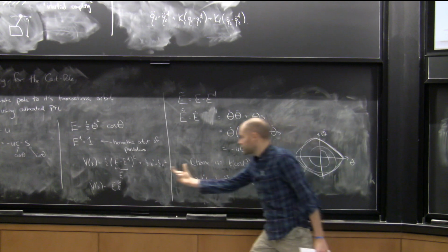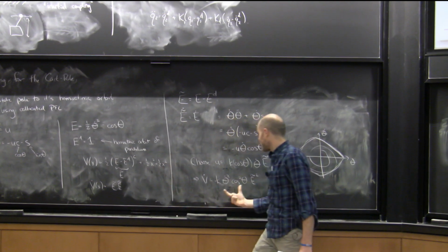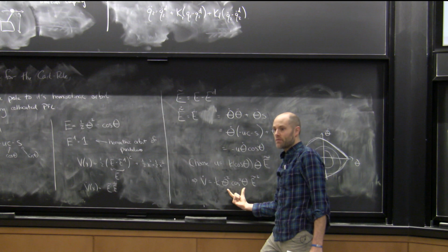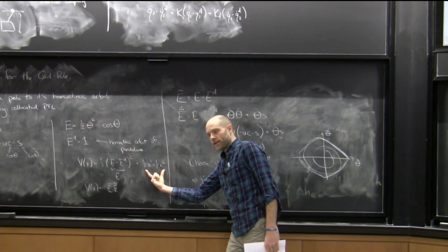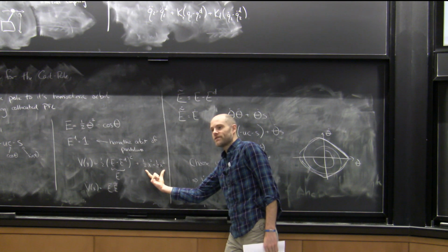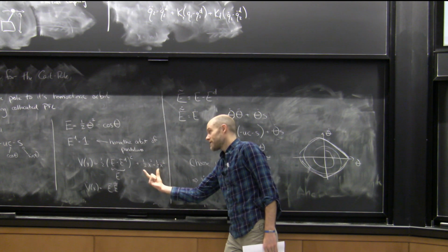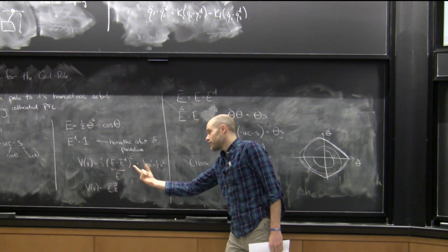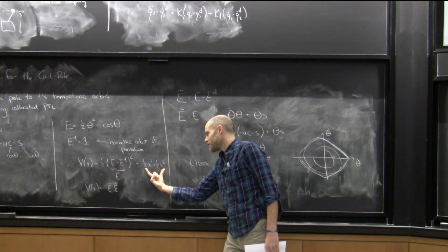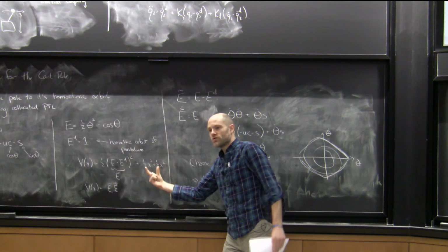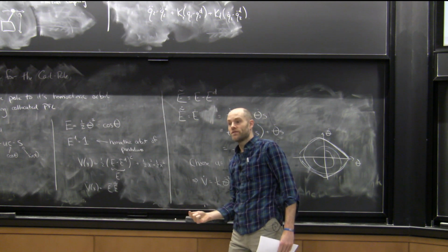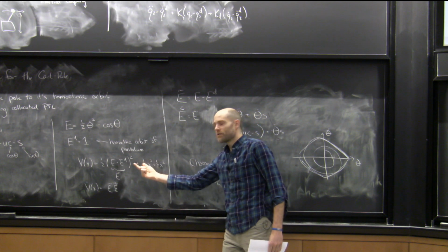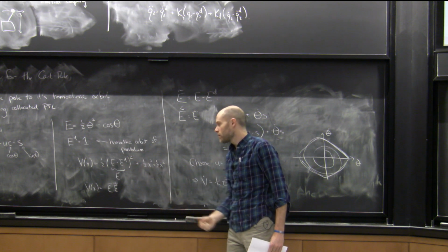As soon as I tack in some terms that do this, I'm achieving this almost, but there are some other cross terms. Similarly, I'm not driving like an LQR controller back to the base of the cart, because I've got all these other things going on. And it's your job, as a Lyapunov function expert, to make sure that those two things don't interfere with each other too much, and you still achieve the task. The language of Lyapunov gives us that power, okay?